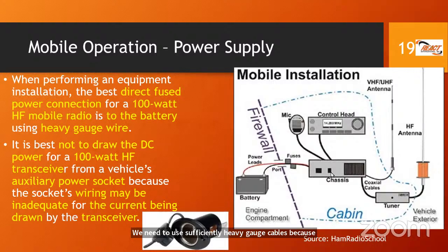And that's a fair amount of power it's going to draw from the battery. So the battery leads or the power cable needs to be of a sufficiently heavy gauge wire. Otherwise, you can have voltage drops, and also you need to put fuses as well, just in case you have a short circuit or in case you draw too much current. The fuses will protect your equipment, or protect the battery, protect your system, right? So that's the point of bullet point number 1.